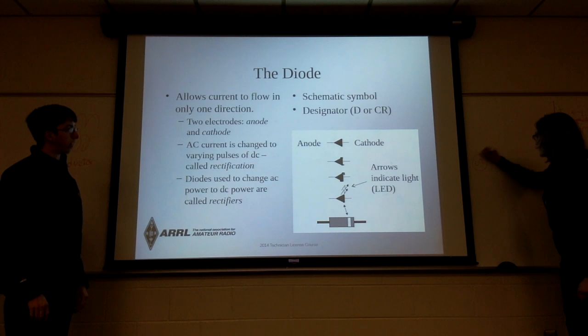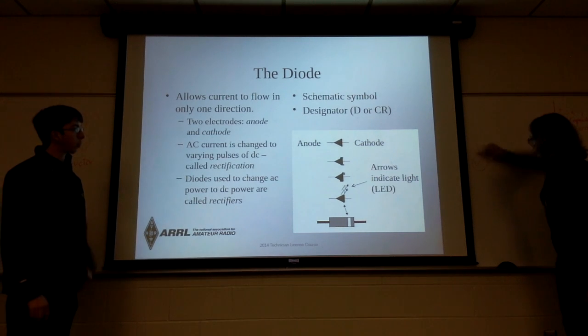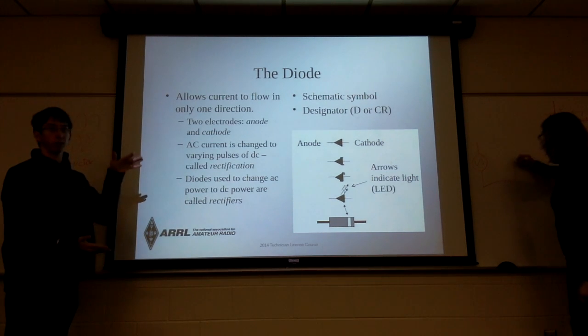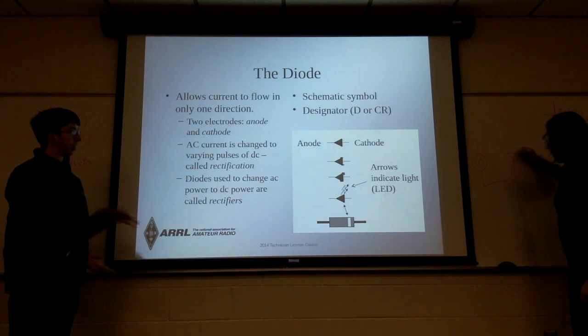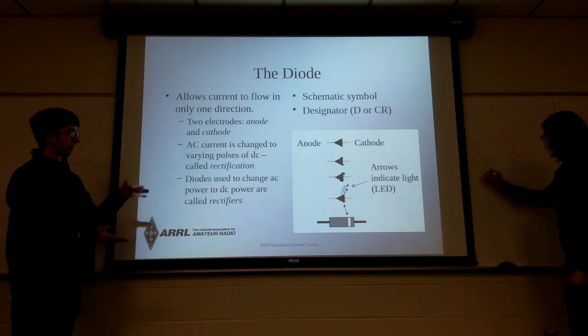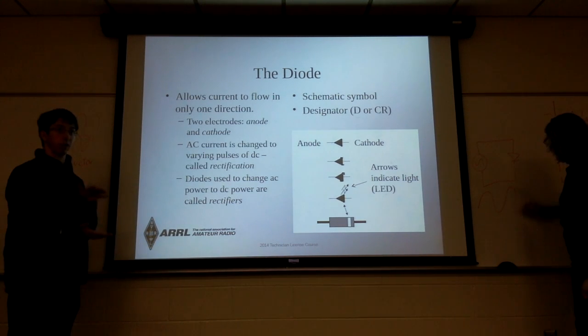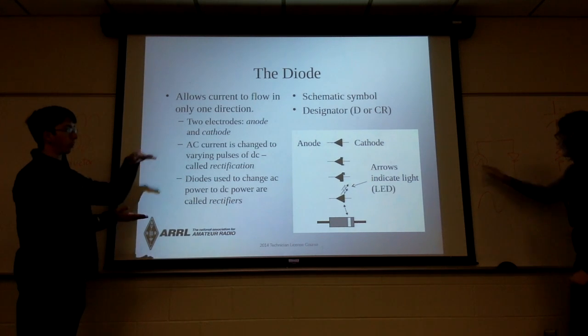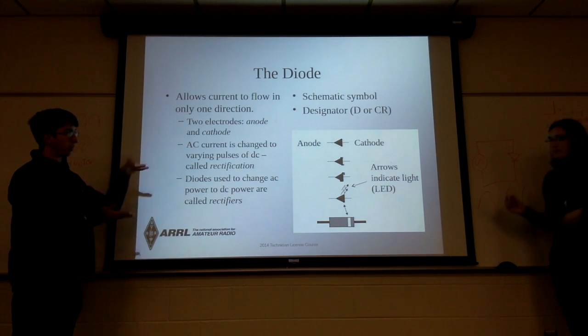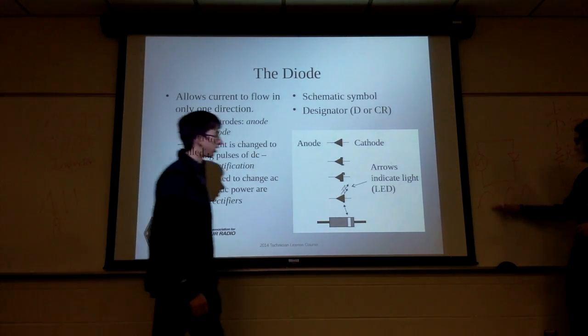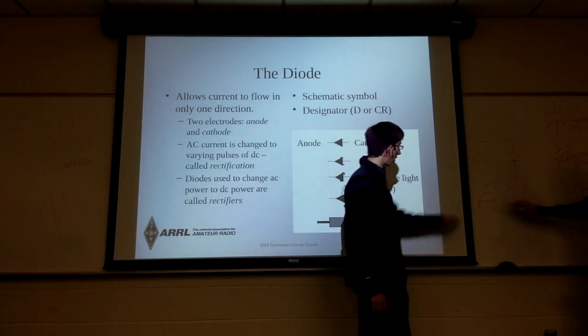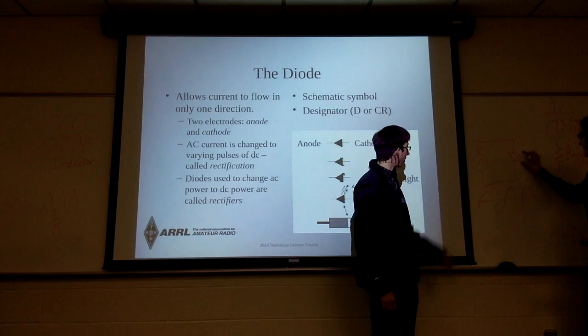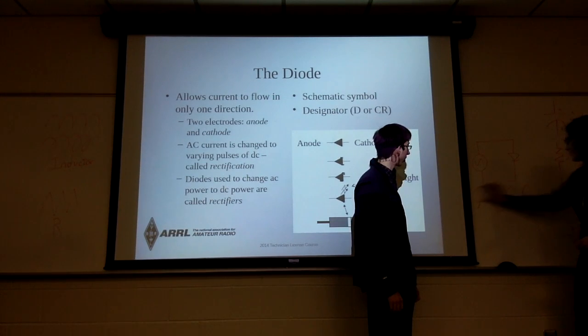And if we feed that through a diode, we're only going to get the top part, or we're only going to get the bottom part. And since it's going to stop conducting at 0 volts, we're going to end up with an average voltage greater than 0 volts. So this right here, this is what it's outputting. It's positive, negative, and the only part that's getting through here is the positive part.